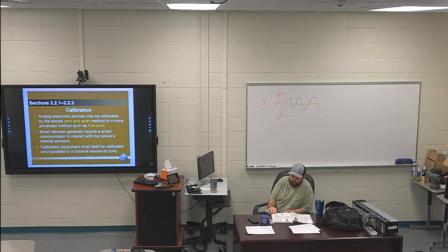Connecting the HART communicator, 223. The whole second paragraph is highlighted going into the next page. And you're going to have a couple questions come out of this one paragraph. If the smart transmitter is used in a digital-only instrument loop with a PLC or DCS, for example, only the first instrument stage requires calibration. If the transmitter must provide a conventional analog 4 to 20 milliamp output signal, both the first and third stages must be calibrated. Note, the third stage calibration is independent of the first stage and has nothing to do with the zero and span settings. The second stage does not require calibration.